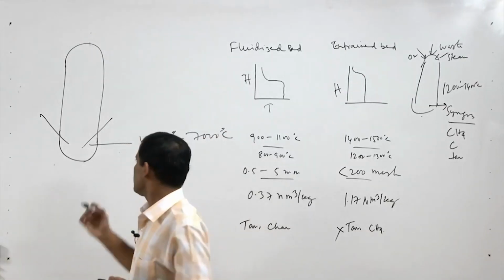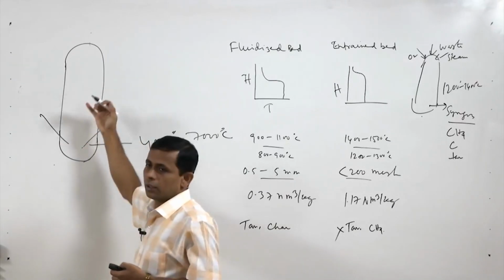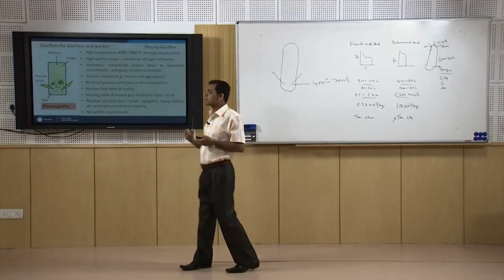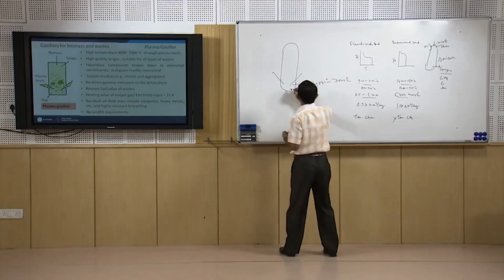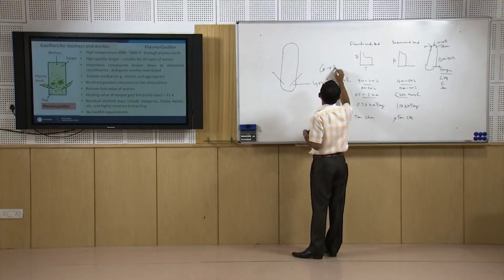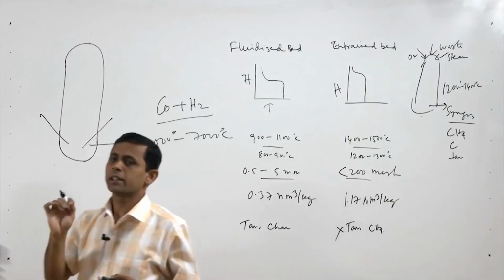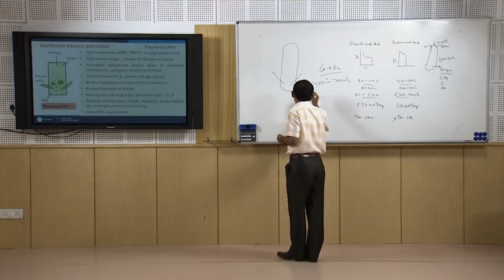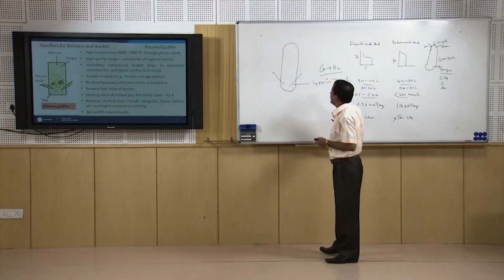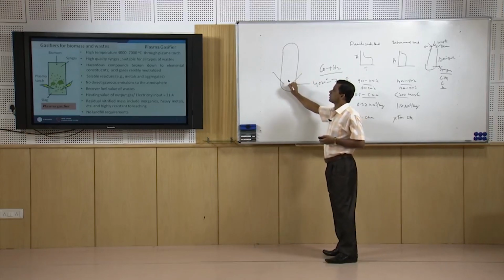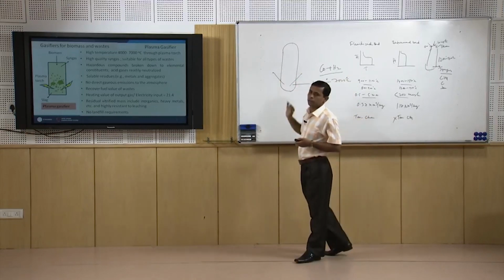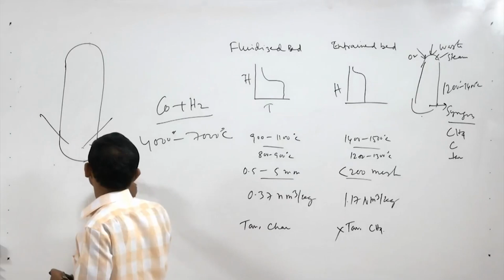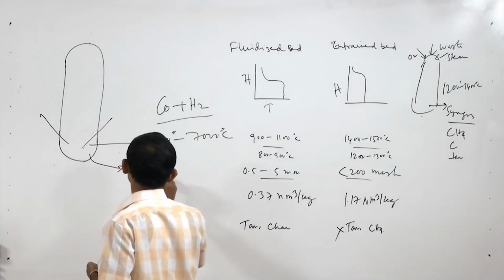This high temperature generated here helps the conversion of the solid waste and biomass present in it to gaseous products, and when carbonaceous feedstocks come inside, a CO and H2 rich gas is obtained under certain conditions. The advantage of this gasification system is that no oxygen stream is required, any type of solid waste can be used here, no pretreatment is required, and the syngas is of very high quality.